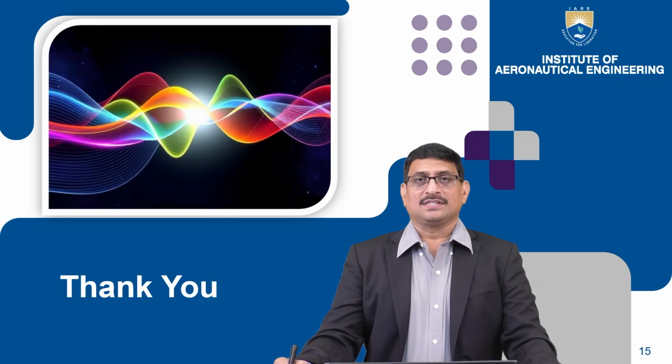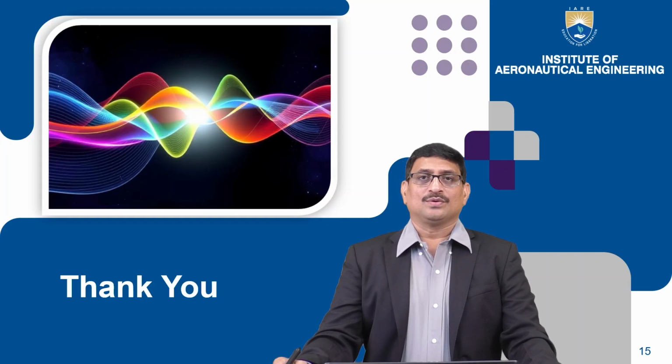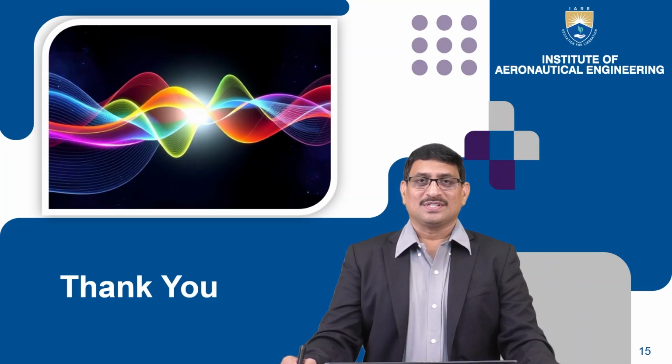The next equation gives the relation between gm and gm naught, the transconductances, where gm equal to gm naught into 1 minus VGS divided by VP, where gm naught is 2 IDSS divided by the magnitude of VP. The last equation gives the relation between the JFET parameters, which is mu equal to gm rd, where mu is called the amplification factor, gm is the transconductance, rd is the drain resistance. So by knowing these 4 equations, and if some parameters are given, the other parameters we can calculate. So this is about the problems on JFET parameters.